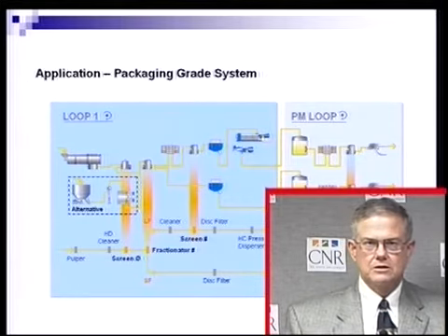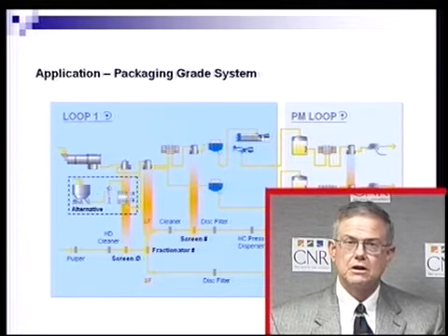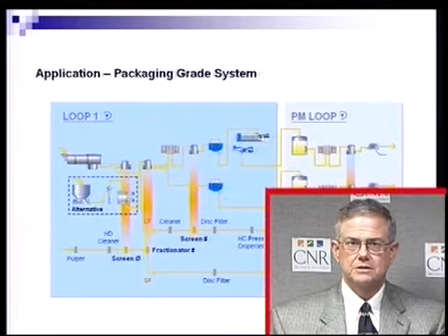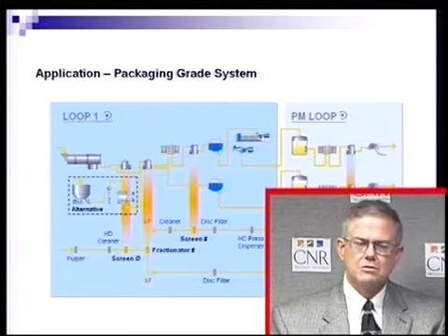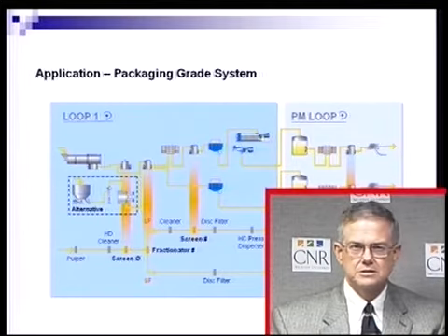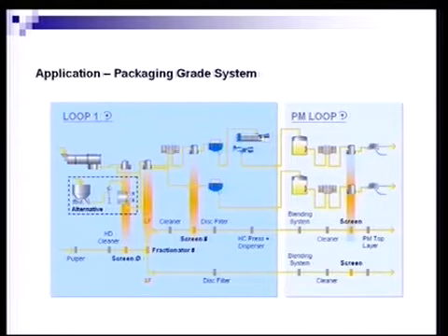The next stage of unit operation is, of course, screening, and we'll do coarse screening with holes in that particular position. Might be followed with fine screening or fractionation, as it shows in this flow sheet. Fractionation is intended to separate long fibers from short fibers and could be done with either holes or slots, but in this instance probably done with slots. Then the long fiber fraction would be further screened with slots in order to remove the sticky debris. Slotted screening is the number one technology that's used for removing macro stickies, or stickies that can cause problems on the paper machine and defects on the sheet.